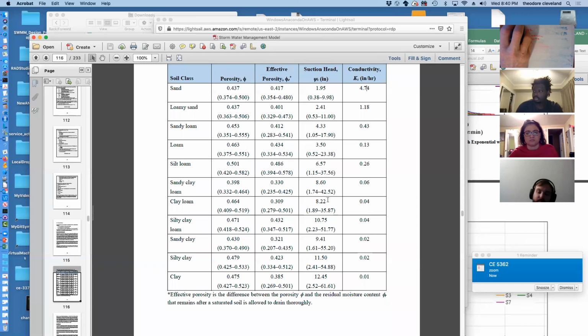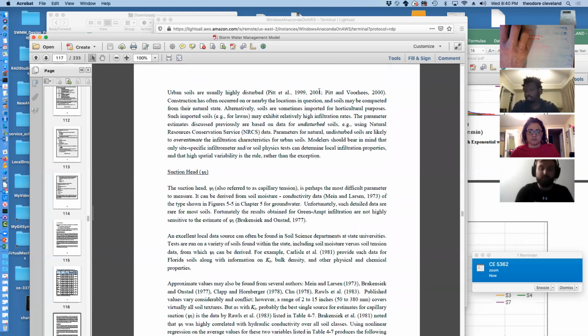And so you can adjust for that compaction by slightly reducing the hydraulic conductivity, reducing the porosity to the lowest value, and then increasing the suction head proportionately. So if we had a soil science class, we could spend a week on all that. Actually, more than, I guess a week would be a month. We could spend quite a while on that. There is a fair amount of wizard hatness that goes on with soil science when we're using it as a modeling tool.